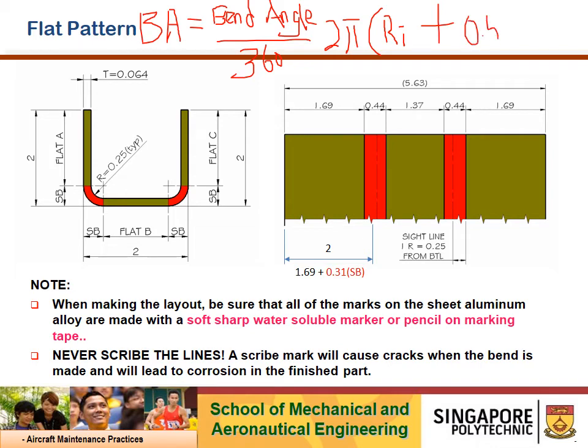And then, to make life easy, I use half of the material thickness, 0.5 times material thickness, in this case. The range is 0.445 to 0.5, so we can use 0.447 times material thickness, up to you.